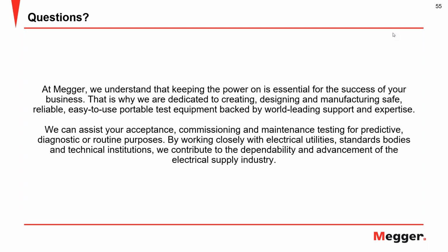All right, yeah, good question. So this is heavily application based. As Robert said, the only method that can represent the measurement in picocoulombs is the conventional method, in which you're actually measuring that apparent charge. So that's the real advantage to performing the test in accordance with IEC 60270 with a coupling capacitor and measurement impedance, as Robert pointed out in the measurement circuit that he showed.